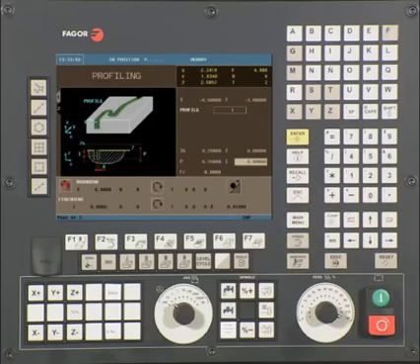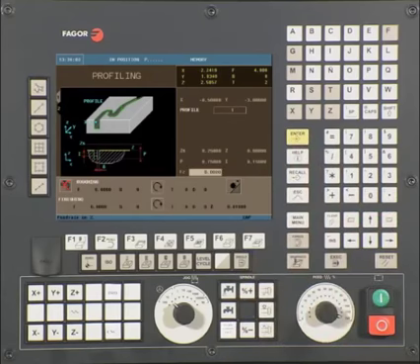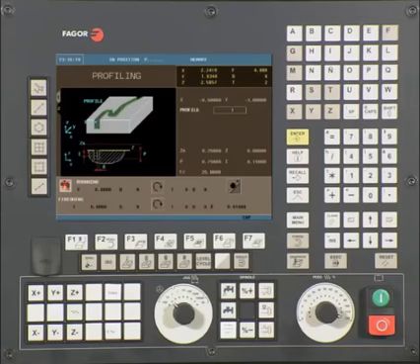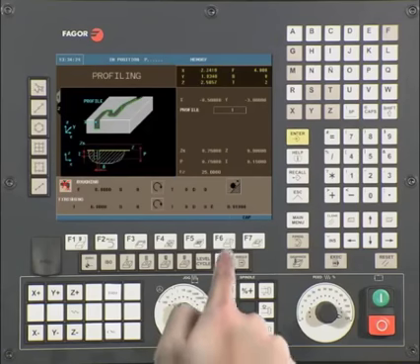I. This is the depth of cut per pass. In this example, we will be using a value of 0.15, meaning it will take 6 passes to get to its final depth. FZ. This is the penetrating feed rate. This value is entered in inches per minute. In this example, we will be using a value of 25. Use the half key to select if you want coolant off or coolant on during the machining process.